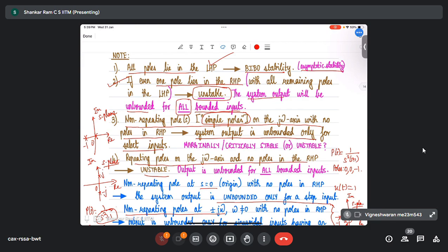And we will see that these concepts are going to be useful in vehicle dynamics. Once again, I'm teaching you all the mathematics, the fundamental theory. Kindly bear with me for the first few weeks, because we need to learn these concepts to understand the finer points of vehicle dynamics. We will use these concepts when we look at lateral dynamics, where we would have heard about understeer, neutral steer, oversteer, and the vehicle losing yaw stability, spinning out of control. Vehicle losing yaw stability has to do with poles going to the right half of the plane. Depending on the speed of the vehicle, the poles of the system transfer function can migrate into the right half plane when the vehicle is in a state of oversteer. The moment the poles migrate there, the vehicle spins out of control and yaw stability is lost. I hope that connects the dots to your question.